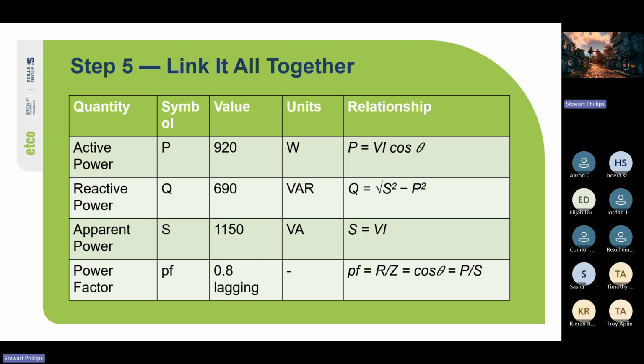It's not so much efficiency, it is power factor. Efficiency relates more to things like losses. For a motor, we have losses in terms of what we call windage or friction, so that would be about efficiency. Whereas for our transformer, our efficiency would be losses in the windings, our copper losses, or our hysteresis losses, iron losses, sorry. So that's more to do with efficiency.